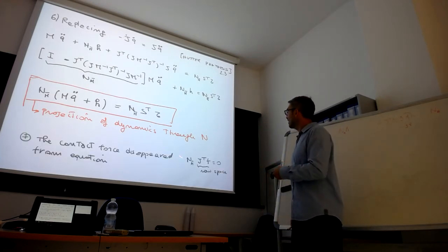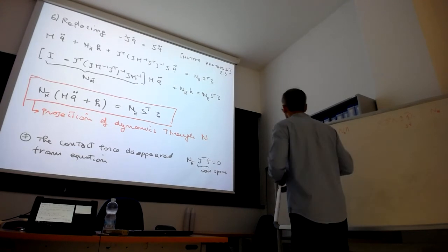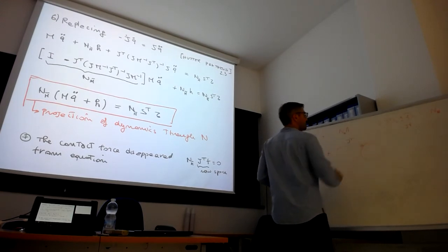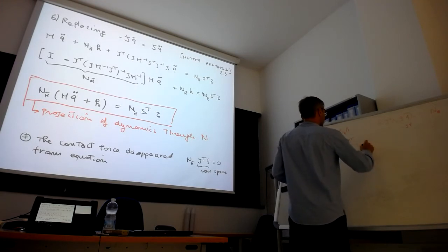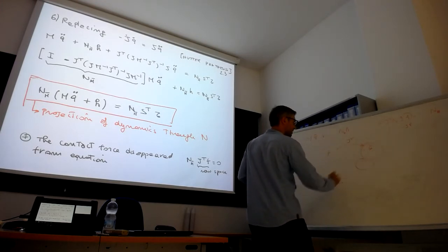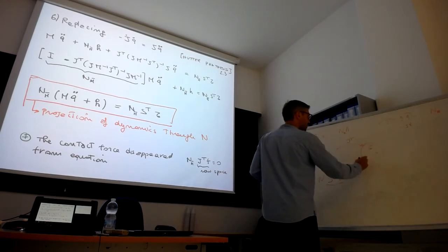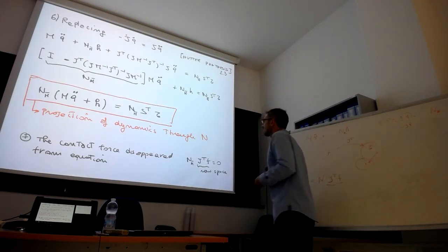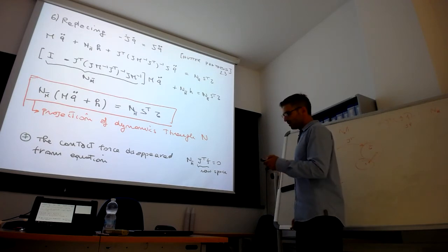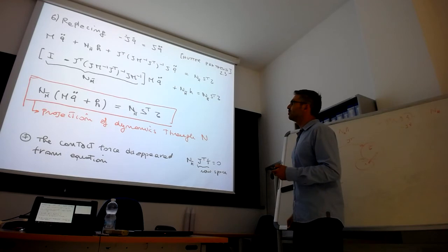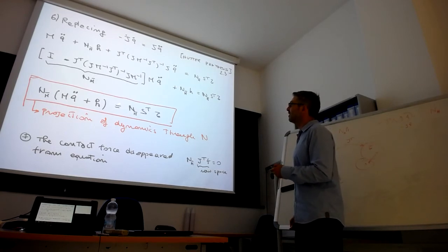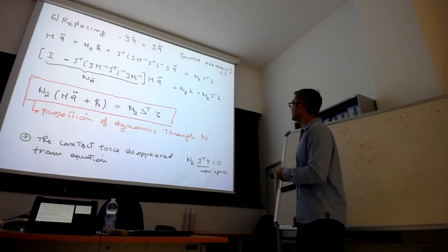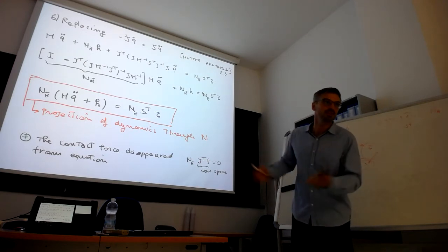And as I said, the contact force disappeared from the equation because we said we have F forces. We go back to the row space with J transpose, so we get some torques. These torques are in the row space, we multiply for the null space projector, the two are orthogonal, so the result will be 0. So this is actually starting from the beginning. You multiply this part for n. You multiply S transpose tau for n, and you pre-multiply n times J transpose F, and this goes to 0, so you remain with that. This is to close the loop.